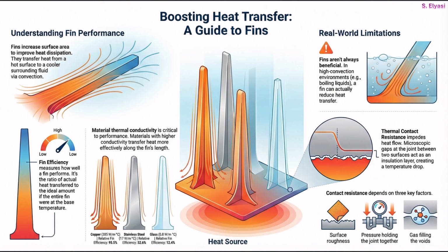Heat transfer fins. Fins are that crucial engineering trick, like the vanes on your computer's CPU cooler, that are all about getting heat away from a surface and into the air. But how well they work isn't always so simple. First, it's all about maximizing surface area. This gives heat more space to escape through convection. Now, to measure this, we use something called fin efficiency. Think of it like this. It's the ratio of how much heat the fin actually transfers compared to the perfect ideal amount it could transfer if the entire fin stayed as hot as its base.